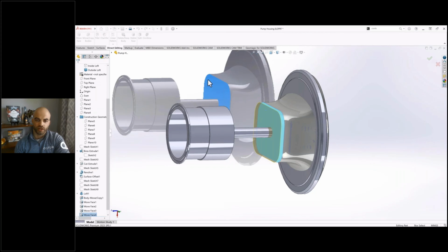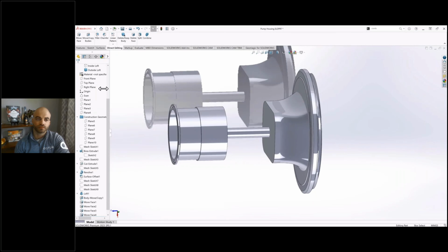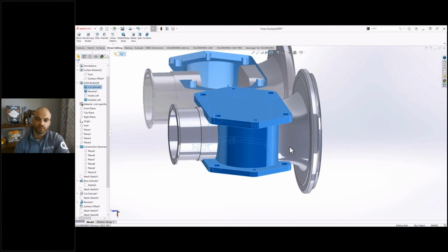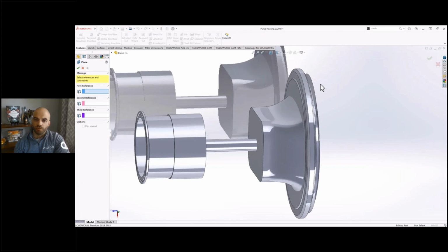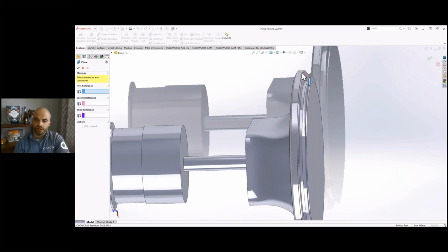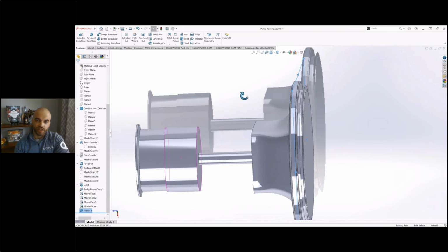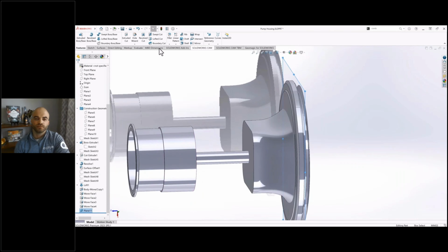I'm just going to push that in a little bit further. And then here we're going to trim that lip of the outside loft geometry back, making sure that it's buried within the revolved geometry.